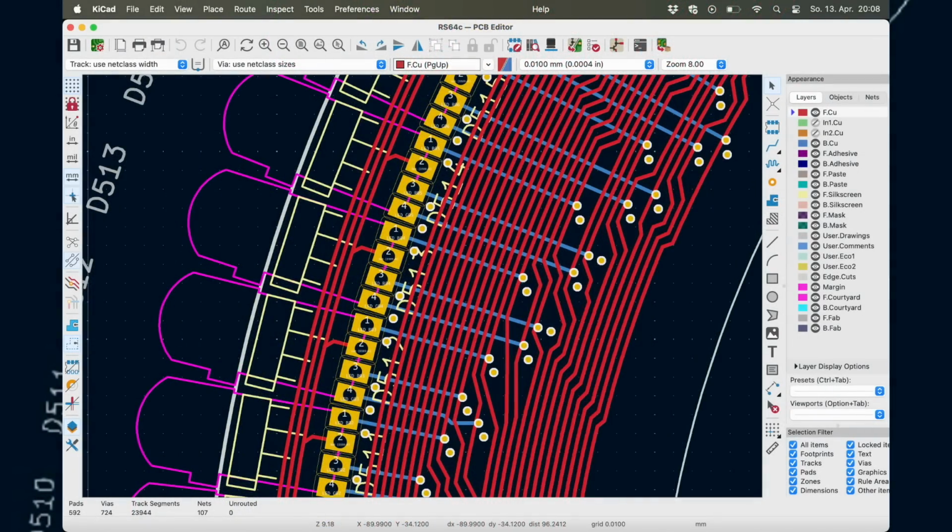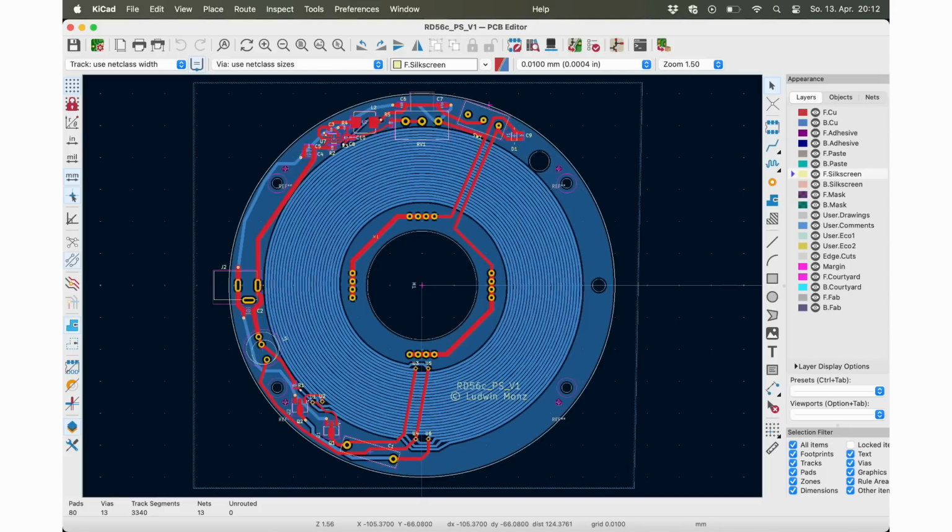In the zoomed-in section, you can see that each signal wire is paired with a nearby grounding wire. This is another important step to optimize return path and maintain signal integrity. The power supply PCB was taken directly from my earlier rotating color display project, so I won't go into detail about this circuit here. As mentioned earlier, the complex coil arrangement of the Royer converter used for wireless power transmission